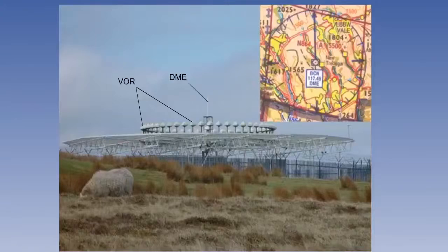Distance measuring equipment, or as it is usually called, DME, is a secondary radar system that enables an aircraft to establish its range from a ground station. DME stations are often co-located with a VOR, which gives magnetic bearing from a suitable ground station. The two facilities together form the standard ICAO-approved Rho-theta short-range line-of-sight navigation aid. Rho relates to range, and theta relates to bearing.